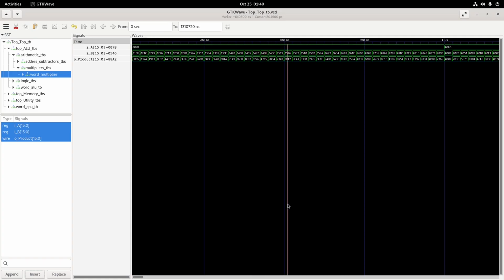I've also tested whether it swaps A and B, because my multiplier is a 16/8 multiplier, not a 16/16. The reason is that if it's a 16/16 multiplier, the maximum output is 32 bits, which is way too big. But with a 16/8, the maximum output is pretty close to 16. So that's how I decided on it. There's a lot of nuances to it.